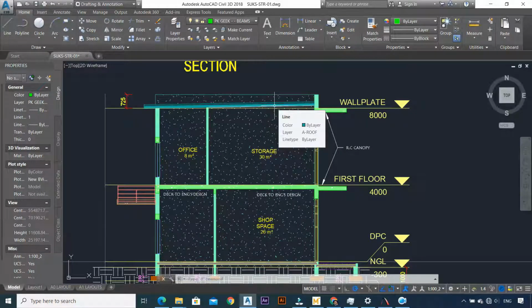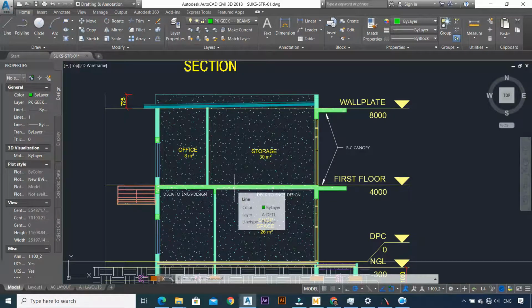Once we get the reaction for the eaves beams, that is the load that will be going to the columns, right? And so we design the first part of that column for that specific load that is coming from the roof and the eaves and everything that is going to be on top. And then once we are done at this portion, we're going to look at the slabs, design for the slabs, and then for the slab we look at the load that is going to the beams from the slab. Then we design the beams that are going to be on the first floor.